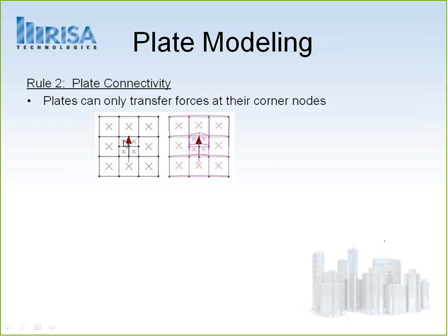But in the interior, we have some smaller plates, and they're really not connected at all. So when you start to put load on them, and as we see that load being applied, they just sort of fly away. They're not actually connected to the nodes of the plates next to them. So they start either just detaching or overlapping, all sorts of problematic things. You probably thought when you put that load there, it was getting to the surrounding plates, and really it wasn't. So if you're going to start submeshing, for example if you need a tighter mesh to represent something in this area, then you really need to submesh the ones around it.